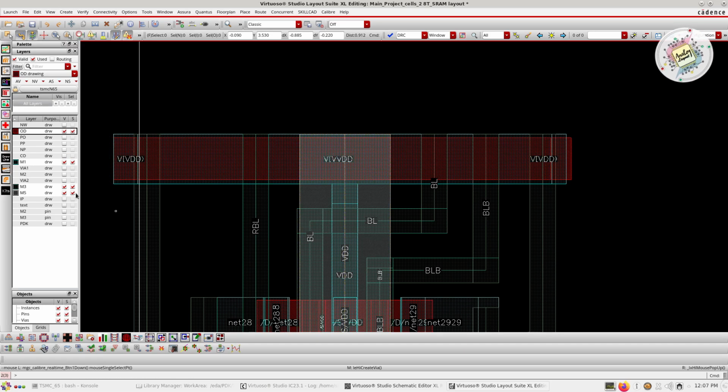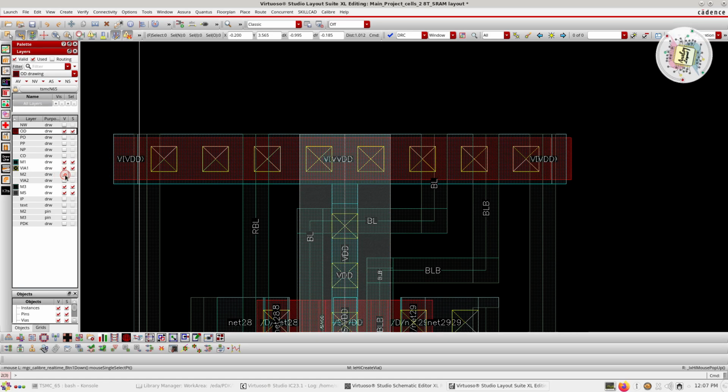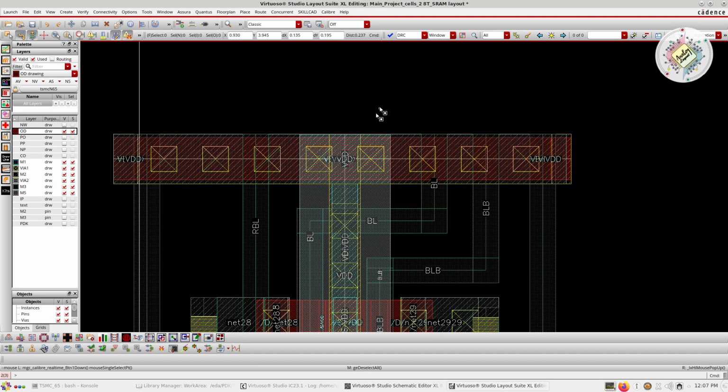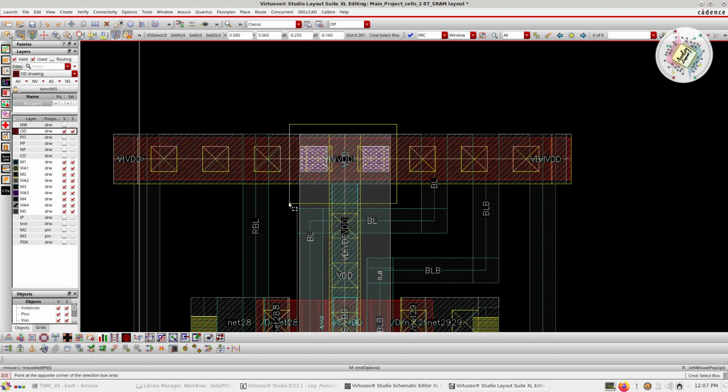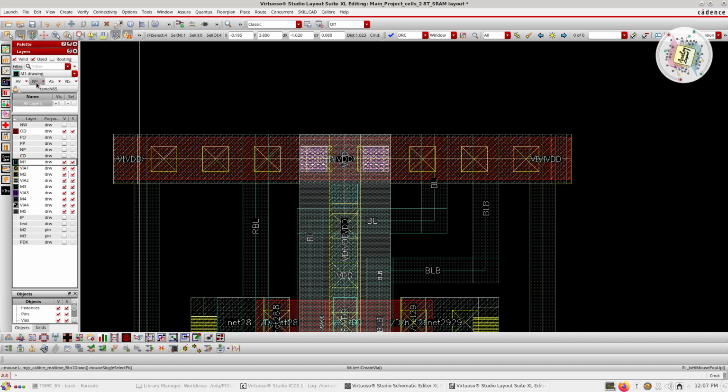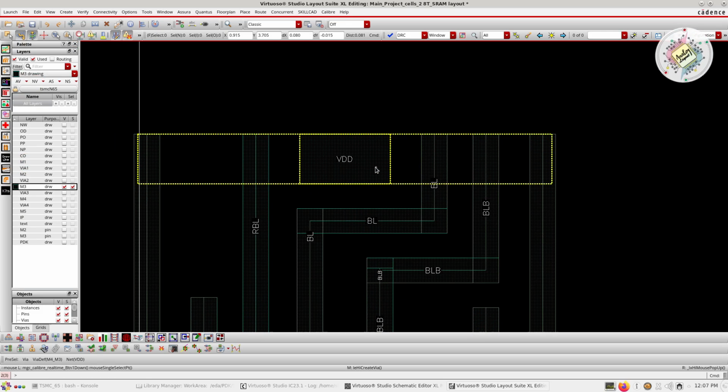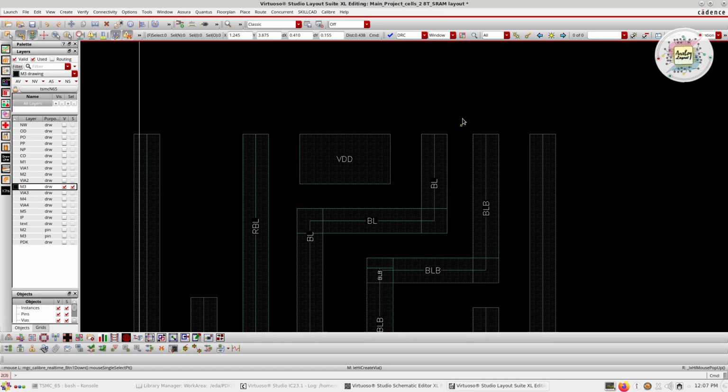If I add 2 vias in this particular area, for example this portion, then this via will be stacked from M5 to M3 metal, right? So let me show you one by one, layer by layer. This M3 needs some minimum spacing between M3 metal to M3 metal. Now here my M3 to M3 I am maintaining 0.12, and on the left side also I am maintaining 0.112. The minimum distance between metal 3 to metal 3 is 0.12.